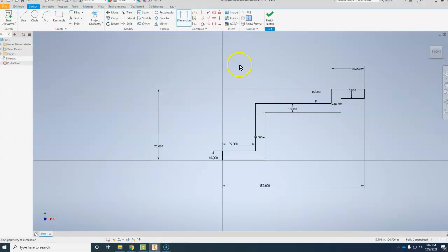So to do that, we're going to go back to Inventor, and we're going to fillet the first one. Fillet this and this. Where's my fillet option? We're going to fillet this, and it needs to be 30. From here to here. And okay. And there we go. That's our fillet. But here's the hard part.